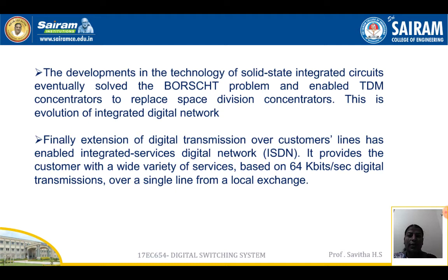The development in the technology of solid state integrated circuits eventually solved the BORSCHT problem and enabled TDM concentrators to replace space division concentrators. This is the evolution of the integrated digital network. Finally, extension of digital transmission over customers' lines has enabled the integrated services digital network. It provides the customer with a wide variety of services based on 64 kilobits per second digital transmission over a single line from a local exchange.